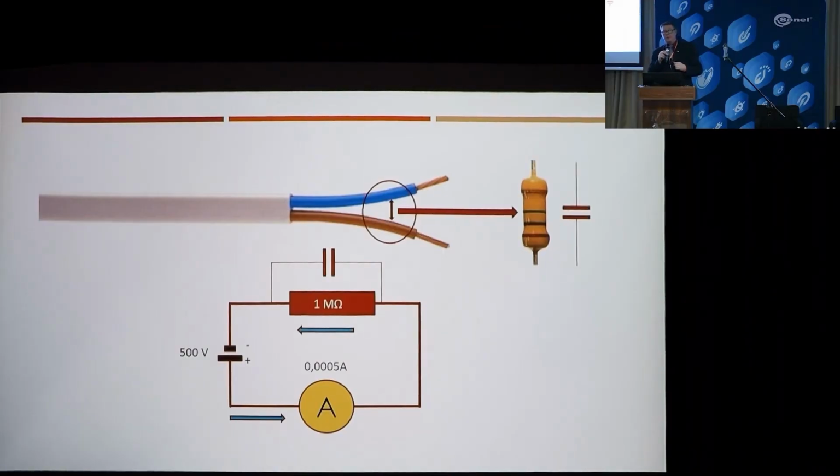At a voltage of 500 volts, the current in the circuit, as we can see, is 0.005 amperes, so very small, right? So we need to realize that these instruments must have fairly precise input circuits to measure such small currents. But please bear in mind that at 20 gigaohms or more, at 40 gigaohms or 40 teraohms, those currents will be truly tiny.